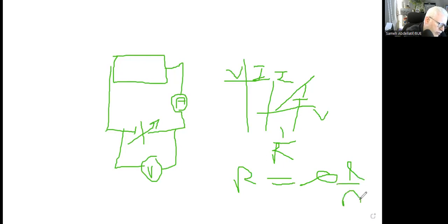Of course, sorry for my very bad handwriting. So R, the resistance, equals rho, which is the resistivity, times L, which is the length of this material, over A, where A is the cross-sectional area. So you can calculate rho from here, and sigma, which is the conductivity, equals 1 over rho. So you can calculate sigma, the conductivity of this material. This is a very simple experiment. You can do it anywhere. I think you can make it in a very easy manner.